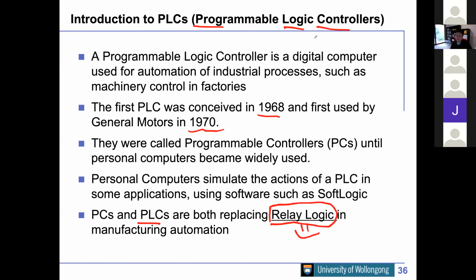PLC is good at. And before the PLC, it was all this relay logic with a lot of switches, physical switches, capacitors, resistors, inductors. It's like analog circuits, but this is a control logic circuit. And PLC is used mainly to replace those, to implement all that logic not by physical relays, switches and components, but rather inside software.